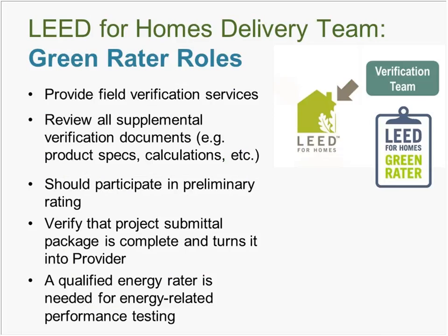But what the Green Rater is responsible for is doing in-field verification inspection, pre-drywall, during construction, doing the final walkthrough, doing a landscape verification. Typically, they're the ones who are responsible for submitting all of the paperwork to the provider, so they're able to sign off on all of that stuff in the field. They're somebody you definitely want to contact early and often, have them involved in the preliminary design rating, in the design charrette. It's required to have them for half of a design charrette to get your point.